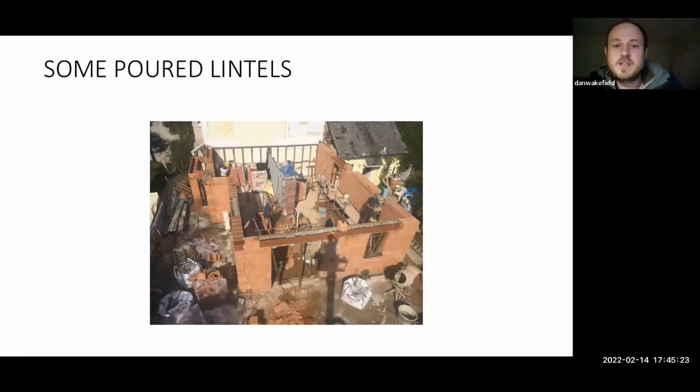And here you can see across the front the concrete lintel, and we're beginning to fill in the other concrete lintels. But you can imagine how, compared to the previous 9 courses, everything's slowed right down again. There's a lot of work that goes into these courses. We're also starting to think about joist hangers for the next course as well.